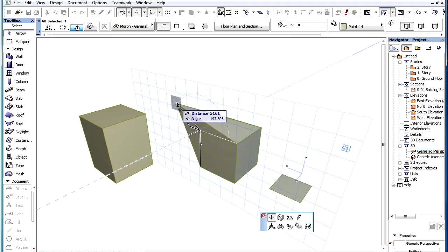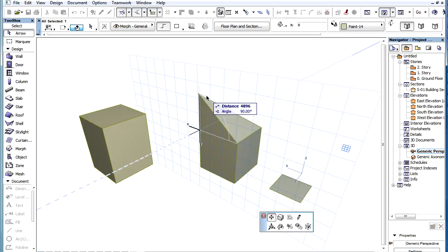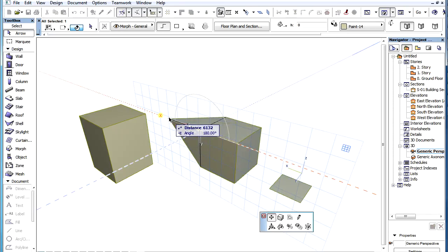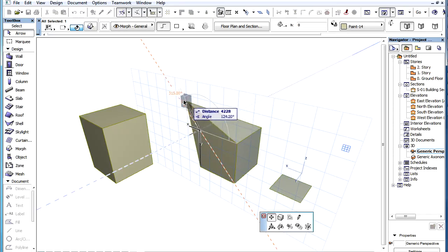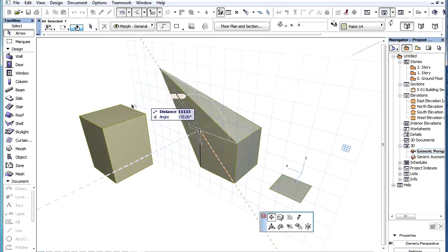Let's say that we find the 315-degree direction in the editing plane and press Shift. The input will be locked onto the editing plane and onto that direction line. If we now move our cursor over the same node of the other element, its point will be projected onto the editing plane. Then the projected point in the editing plane will be projected onto the locked direction, and this point will be the input point. In either case, the dotted projection line will show exactly what point will be used for input and how the program arrived at it.